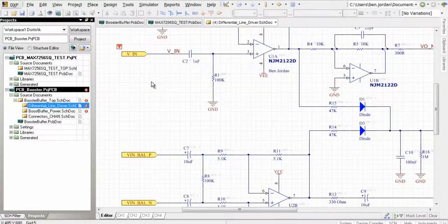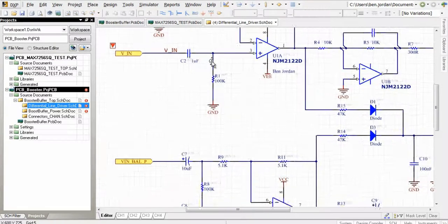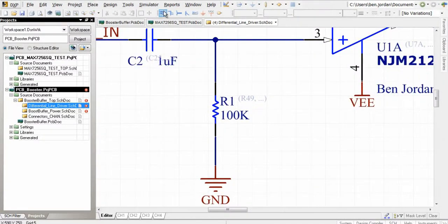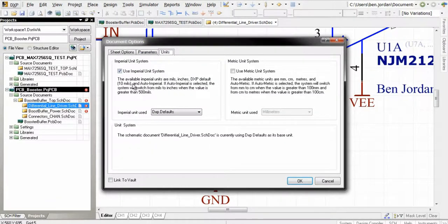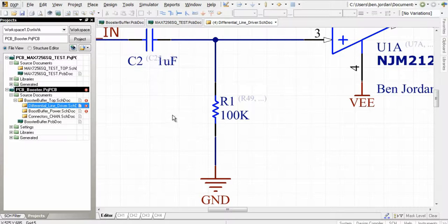One of the most critical aspects of electronics design is the ability to control precisely where the mouse cursor can take actions. The most basic element of the cursor snap system in Altium Designer is the grid, and you can operate grids in either imperial or metric coordinates. The grid is pre-configured with specific steps.